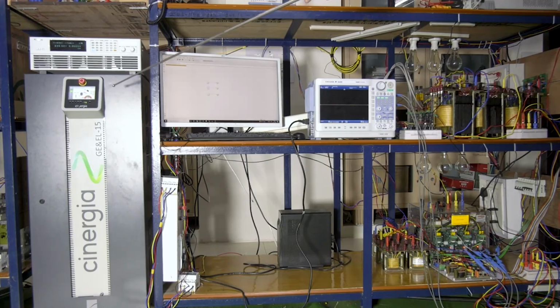Also, notice that after the inductors, the wires are passed through the LEM current sensors. For voltage measurements, sensing is done near the MCB input and the sensed signals are connected to the LEM voltage sensor board. The setup is ready for demonstration.